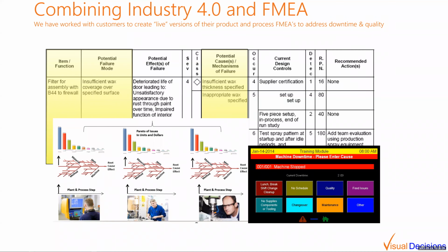The probability of detection is a little bit more tricky, but essentially what these systems do in terms of the impact on probability of detection is, when you think about being able to track those detailed process variables and so forth, if you can start to tie some of those things to where they either directly point you to that failure mode, or if you can set them up so that indirectly you can infer that you had this particular type of failure from those, now your probability of detection goes way up because of those different systems that you're putting in place and those different capabilities.